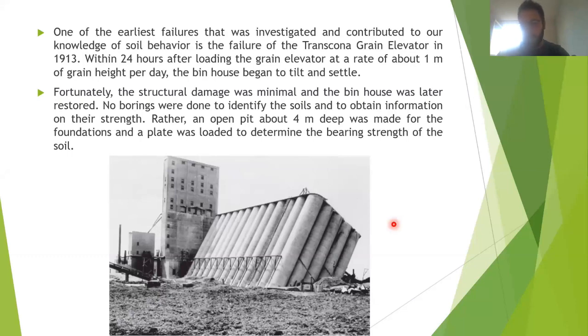So if you fear that your soil can be aggressive, you just do some chemical tests, and then based on what values you get, you put the soil in one group, one category. Then you know how to design your concrete recipe, so it's not going to be damaged because of soil aggressivity or water aggressivity.